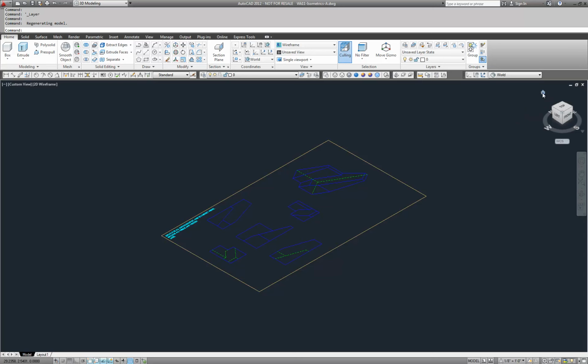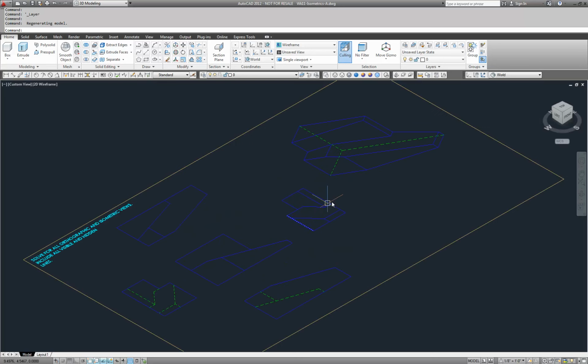Now to keep that, once I have parallel picked, I'm going to right click. I'm going to go set view as current home. And that way it won't go jumping in and out. Sometimes AutoCAD wants to try and help you.